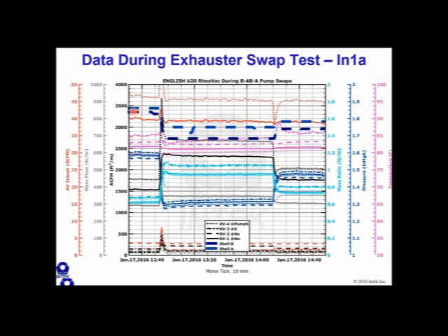And so that's what this data shows here, is that if they turn on a second vacuum pump, these dark blue lines are their measured condenser pressure. So if they turn on two vacuum pumps, they can actually reduce their condenser pressure here by about 1/10 of an inch, 1/10 to 2/10 of an inch. So as part of your troubleshooting efforts, if you suspect high air in leakage, the very first thing you can do is turn on another vacuum pump and try and lower condenser pressure.